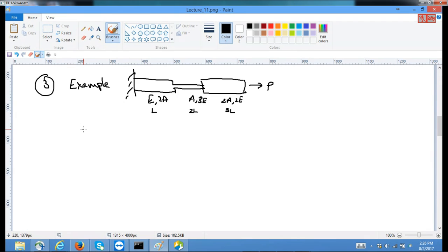We showed this using two noded elements, one element for each segment. This is segment 1, segment 2. We obtained u tilde of x in each segment by doing the complete example problem with the assembly, substituting the boundary conditions, solving for the unknowns, and then obtaining u tilde of x in each segment. That is what we have done, and this completes chapter 2.